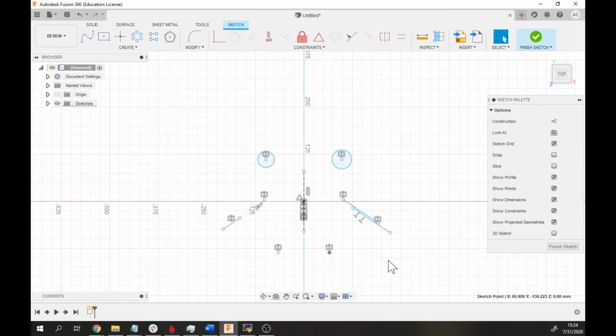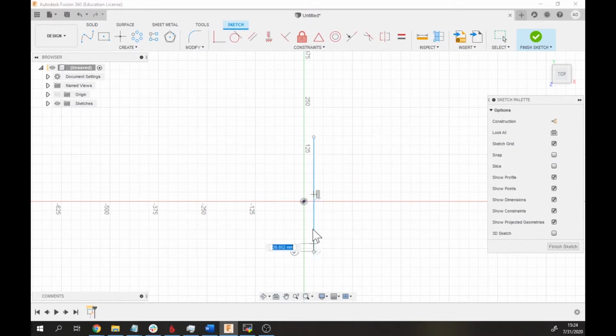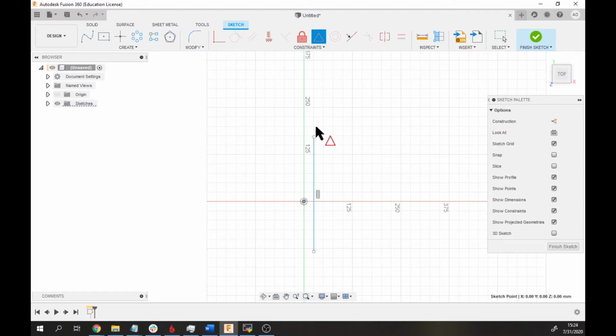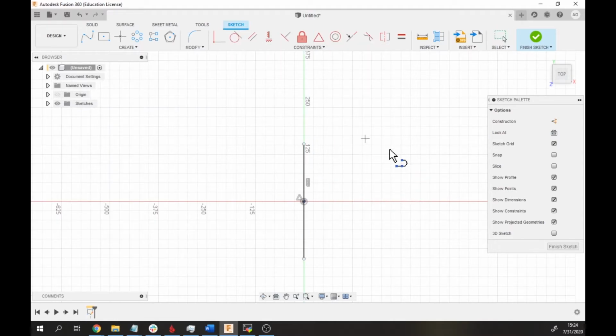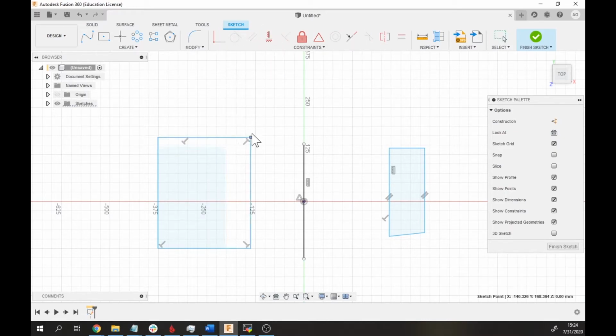This can be very handy if, say, you're drawing a line and you once again midpoint that to the center, and then you're drawing 2 boxes around the outside here. So I'll just throw some quick boxes out. We'll use our perpendicular tool to rein these back in. And then I'm going to delete this parallel constraint and make this horizontal vertical, so it's not referencing anything else. It's actually, sorry, it's perpendicular to this line here.